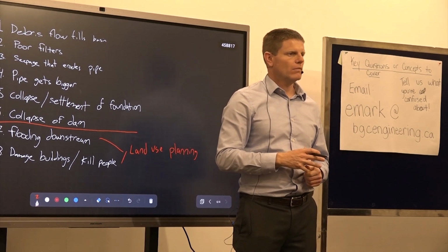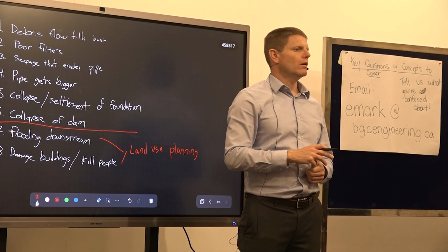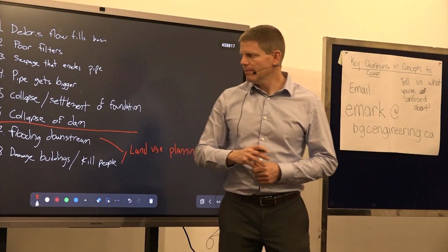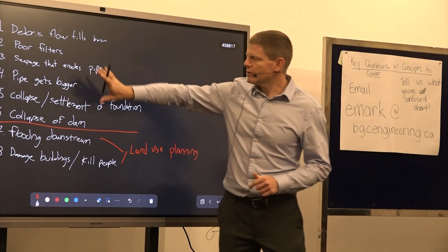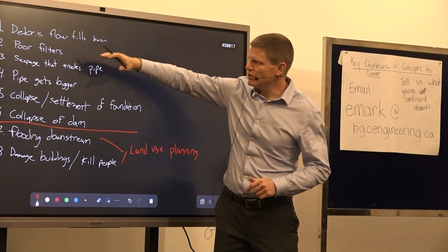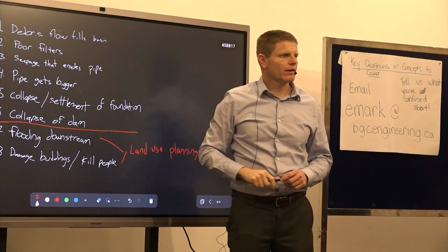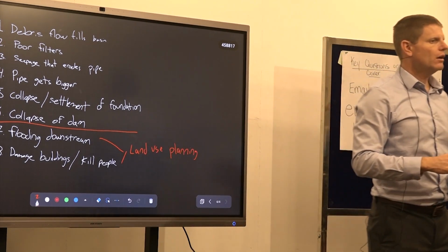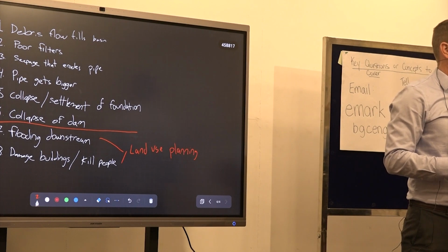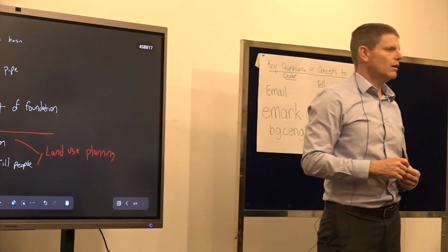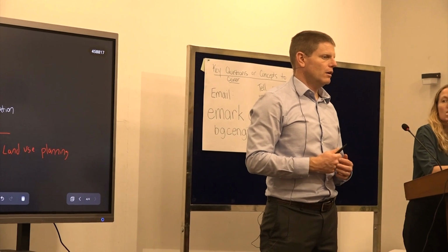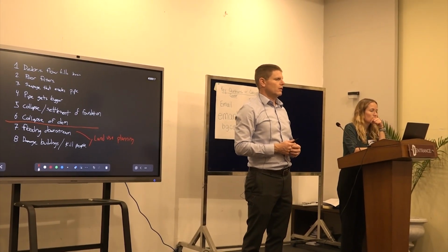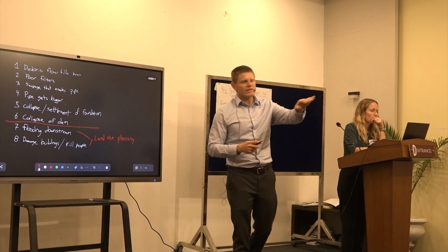For this, I have written one point: periodic inspection of the dam should be done and routine maintenance is mandatory. Okay, how would the routine maintenance of the dam affect these items? Now we can monitor whether our filter materials are working properly or not. And if not, then we can construct check dams and replace the filter material with proper materials as per the site conditions, analyzing the geotechnical analysis. Okay, that's a good one.